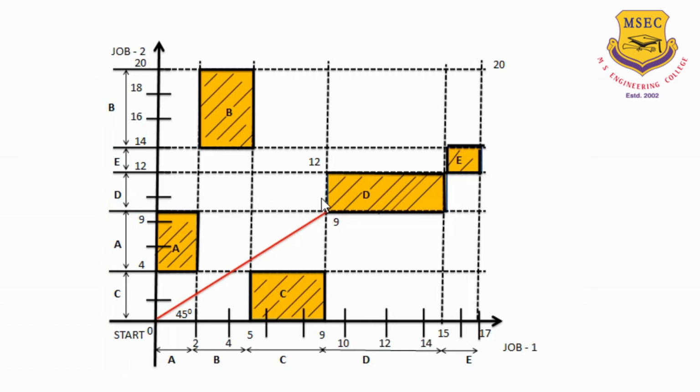Here I got another 3 units of time, and that's idle time for job 1. So the vertical line indicates that there's idle time for job 1 and the work is getting processed on job 2 on machine D, right? The time taken up to this point will be 9 plus 3, which is 12.